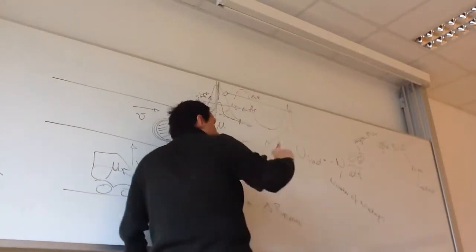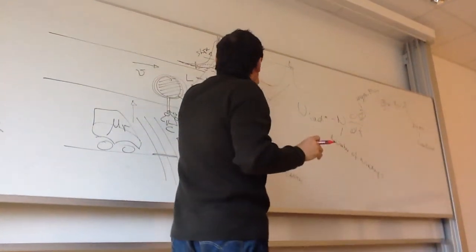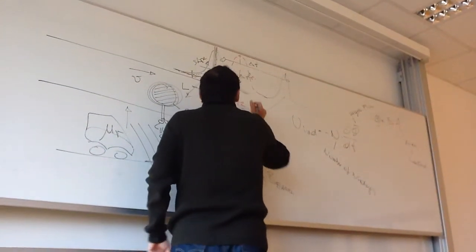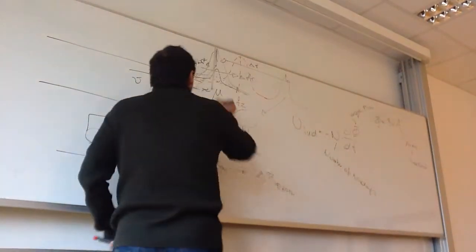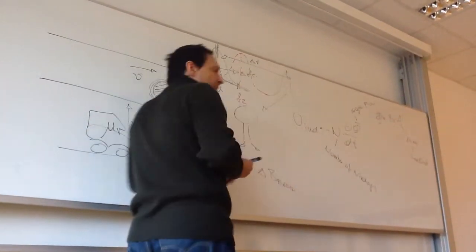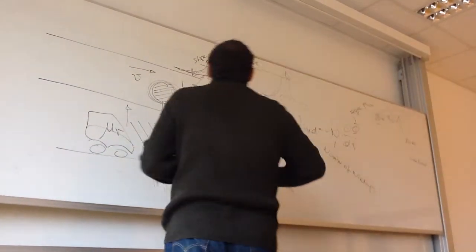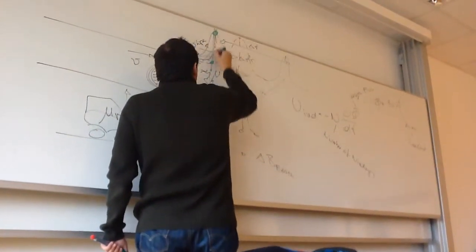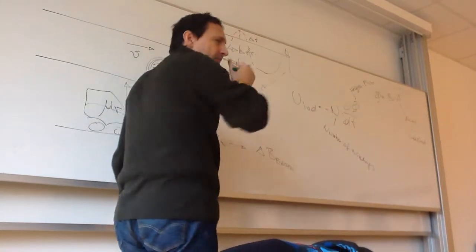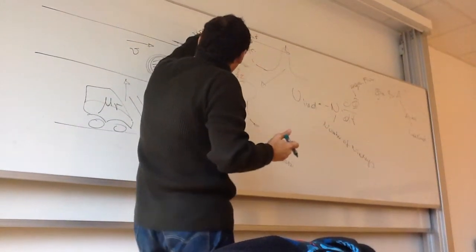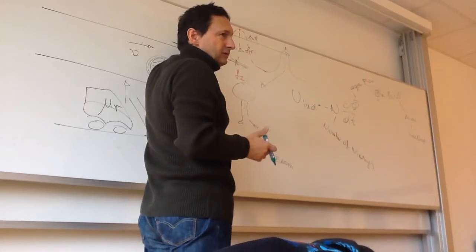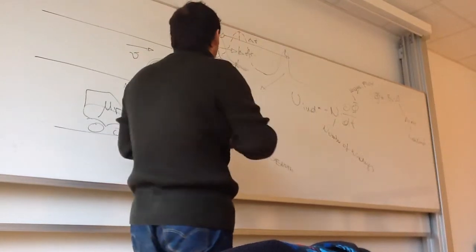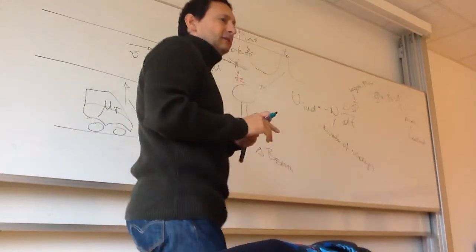It won't change the way it looks, but it will shift the resonance frequency from F1 to F2. So the curve will be shifted, and what you are measuring is the difference between that voltage and now we are here. So the voltage will go down, and after the car leaves, the voltage will be restored to the prior value. That's what's going on. You shift the curve of the resonance circuit.